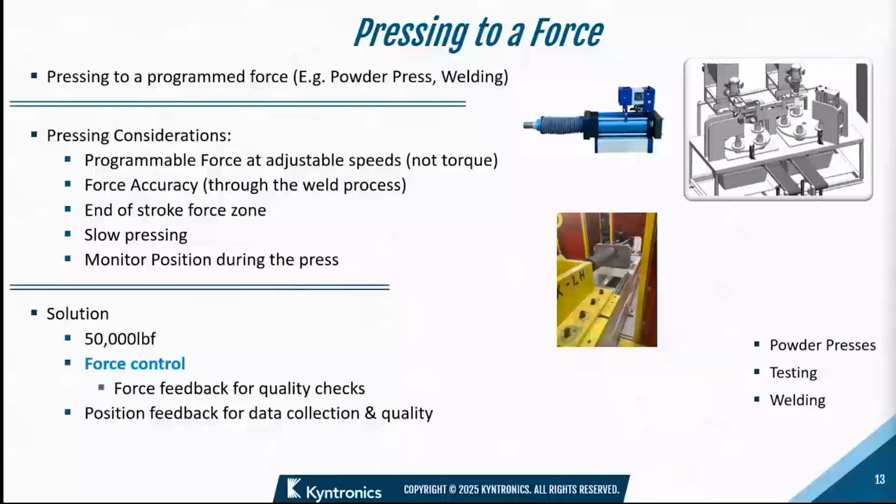Pressing to a force is another unique, different control mode that's available with our solutions. Some of the considerations, again, programmable force, adjustable speeds. So once you go into force mode, it'll go to whatever speed you have listed. Slow pressing, those sort of things. Monitor position during the press, so you have that feedback. So you have both position and force feedback devices.